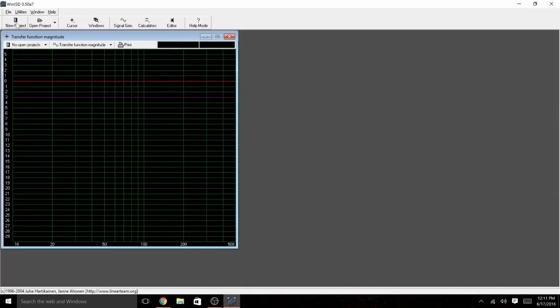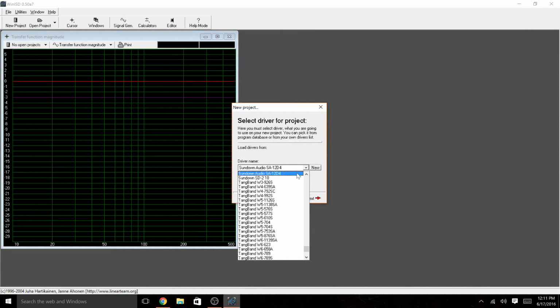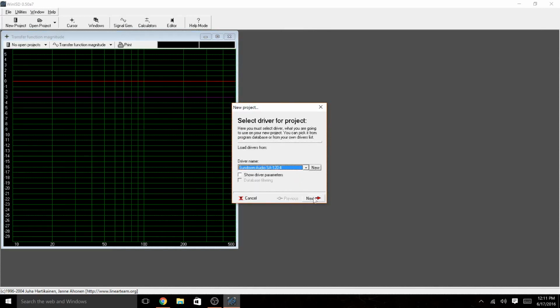Okay, so now you can get back to new project, and for those that already had theirs listed, you can pick up here. So go to the drop down, search for your subwoofer, you should have it now, and click on it, and then go to next. So right here is the amount of subwoofers you'll be installing. I'll only be doing one, but you can do up to 100. And right here is how you'll be mounting it: normal, which is a description right here, or isobaric, there's a description right here. Most people will be doing normal, which is what I'll be doing. And click next.